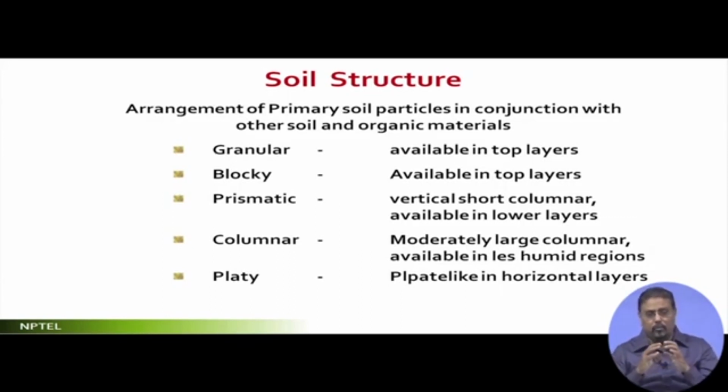The blocky means different kinds of blocks. The granules are held together, and ultimately they make individual blocks, and the blocks are being held together. They are also found in the top layer. And these are the layers which are very useful. These are the kind of top soils which are very useful. I will explain how. There is something which is prismatic, the prismatic form, that means a cuboid kind of thing, short columnar. And there are columnars which are a little bigger, meaning longer heights.